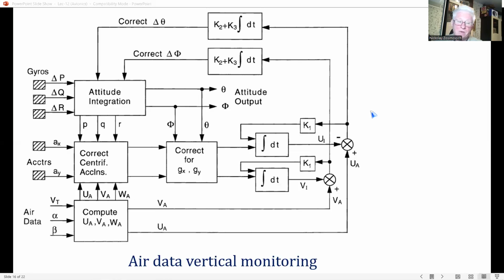The computing power available, however, within the embedded processor in the solid state AHRS enables a more sophisticated leveling, or as sometimes called erection loop, with variable time constant to be implemented. The erection cutout strategy during maneuvers can also be made more adaptive.